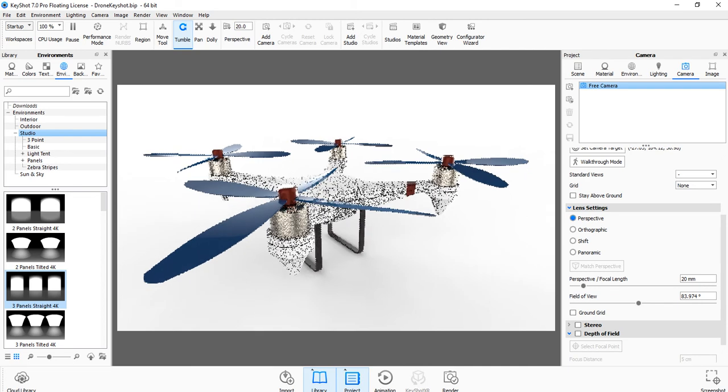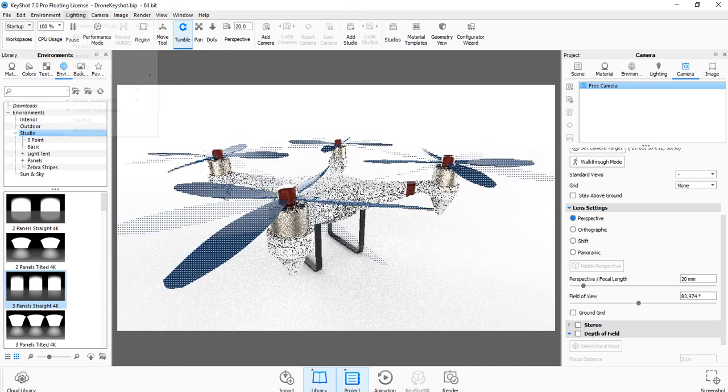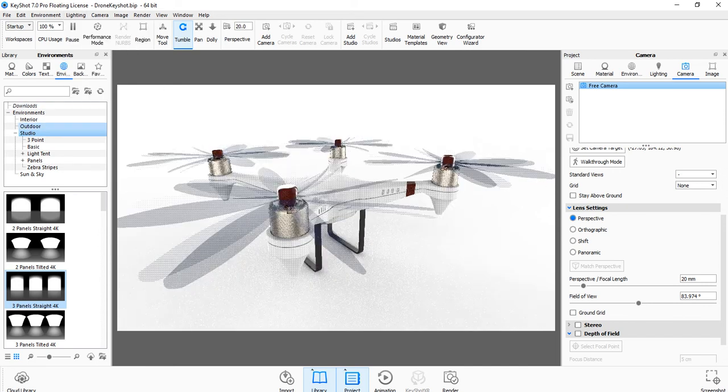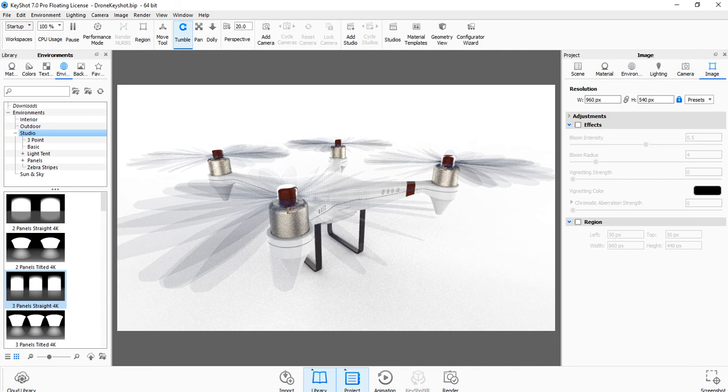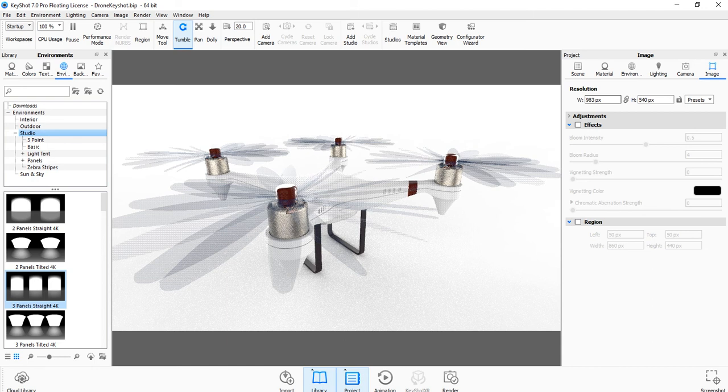I'm going to turn on my motion blur. I'm going to turn on my global illumination and my ground illumination and my interior mode. And I'm also going to go to my image, and just like our previous images where we would set up our sizing here, I'm going to unlock this and set this to 3000 by 2400. Now, if they fixed it, this won't be a problem. We'll see. Nope, they didn't fix that part. Okay. So I set it to 3000, and it just stops.